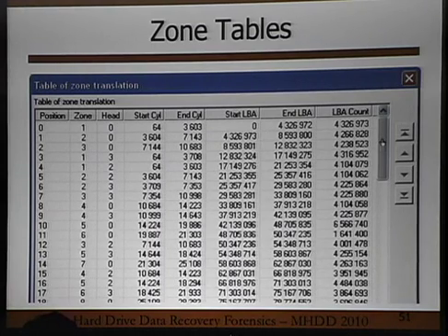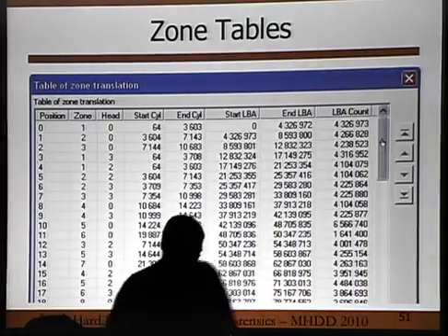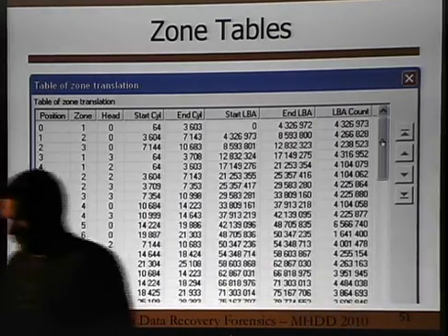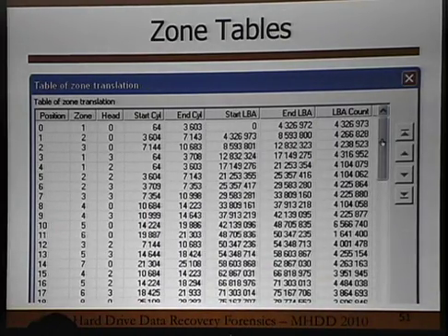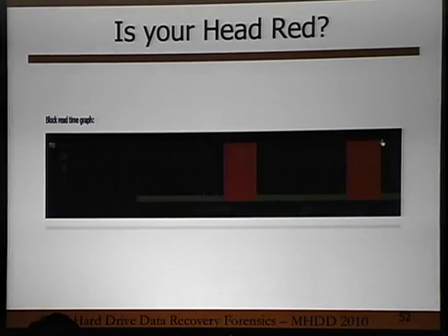So on the drive, in the system area, they said, what is the fastest part of my drive on my platters? And so from 0 to, in this case, 4,326,000, blah, blah, blah, LBAs are all on one side of one platter. So I got basically a chunk of 2 meg of data before it moved to another location on another platter. So if I could read, say, 75% of the disk, I may still have Word documents or pictures or something else that I can still interpret. Then I can go and fix the one bad head and then fill in the hole for the one that I read, if that makes sense.